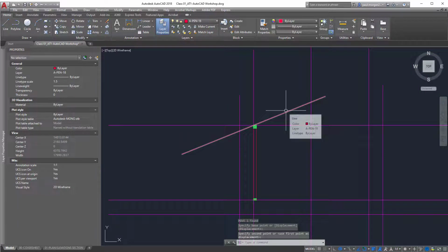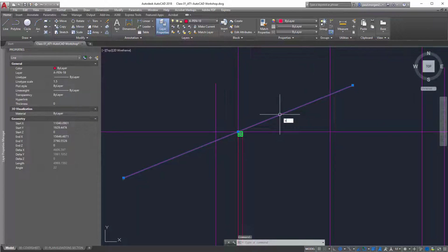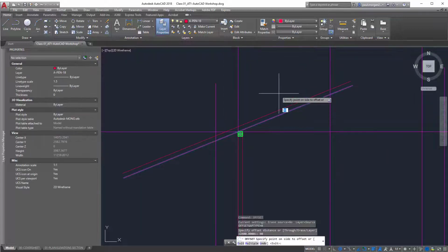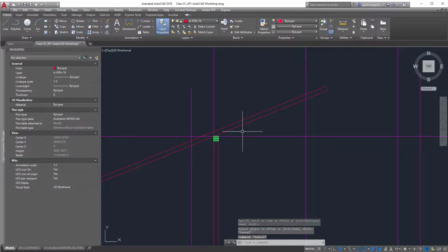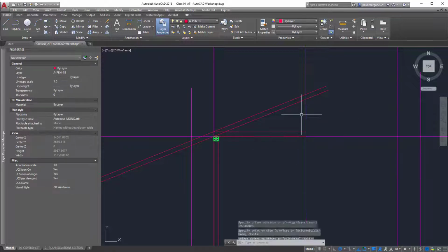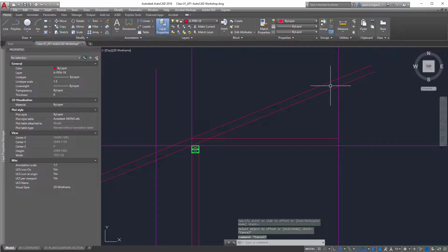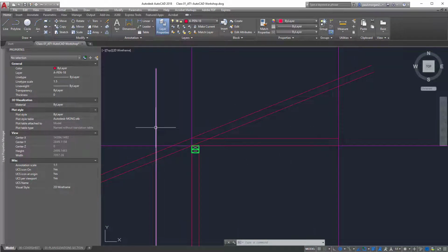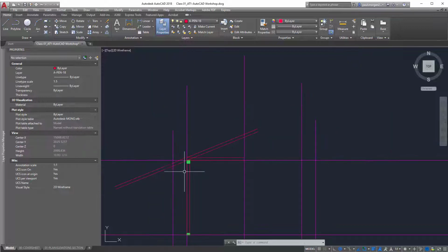Now we're just going to use the offset command to actually fill out our truss. So offset 90 mil, because they're all 90 mil elements upwards. And then I'll draw another line from this point to the midpoint of the building, and also offset that 90 mil up. Okay, so you can start to see the idea of how we're getting this truss shape. And then these reference planes actually act as our guides when we want to trim these back.